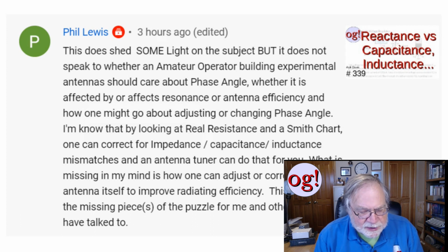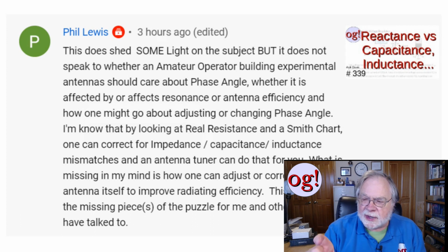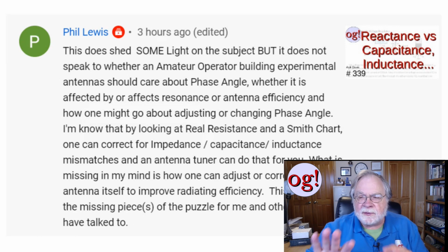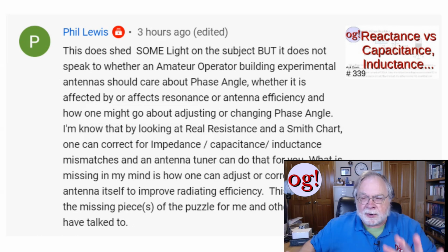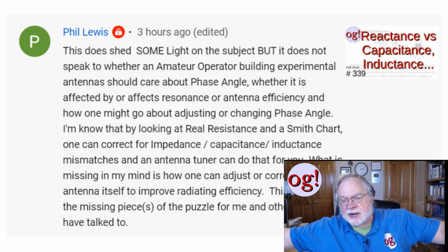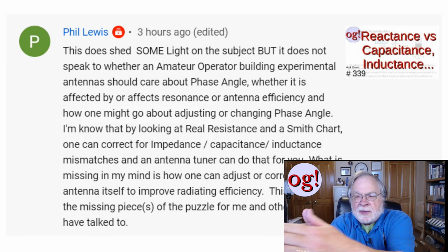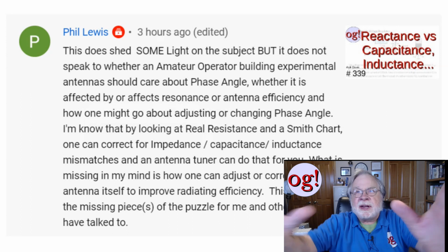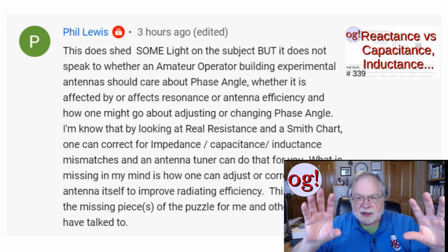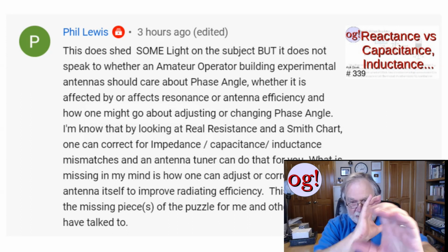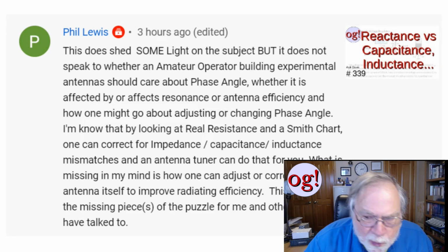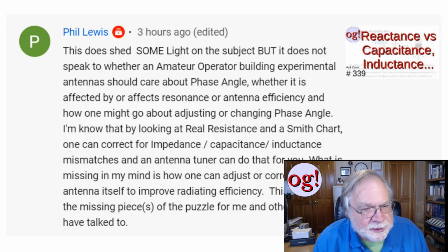A lot of the military's radars, where you're dealing with 10 centimeter wavelength, can phase multiple arrays, different phase shift across them, to point the beam anywhere they want. And because they've got so many antennas, they can point it very accurately in a nice tight little beam once you get out past the near field.